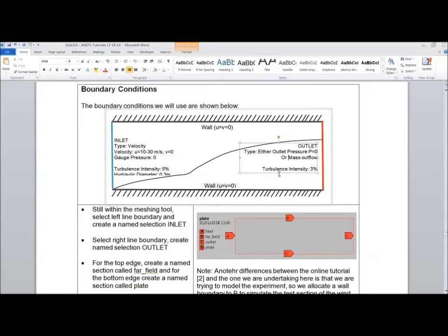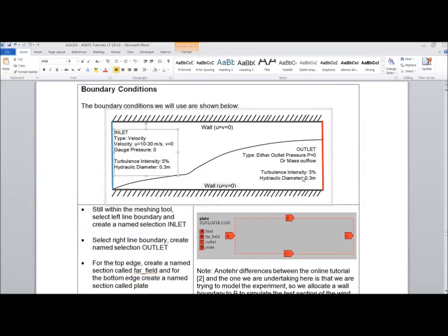And we are going to apply turbulence modeling later on, so those boundary conditions are still retained there in the description. Along the top part of the test section, and obviously along the bottom plate, we're going to have the no slip, U equals V equals 0, and that will lead to this development of a boundary layer, which would hopefully look a bit like that.